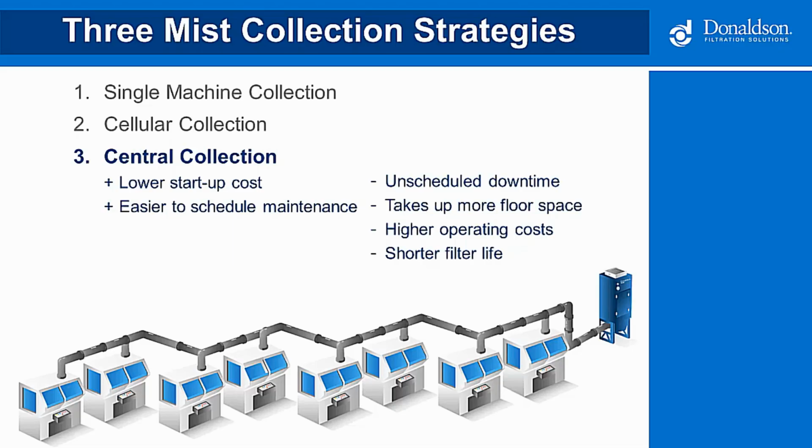Installation costs could be greater depending on the amount of ductwork that's required, and you have more potential leak points throughout the plant. There's no forgiveness for that challenging oddball application that may get mixed into the process, and there's no flexibility for changes in the process or if you need to move equipment around. So when you're using a cellular or a central approach, I recommend that you work with a qualified filtration expert to provide the right system and duct design for your application.